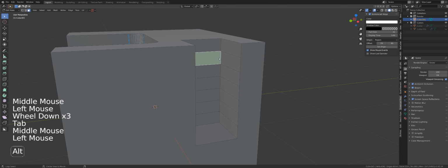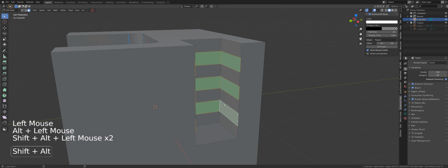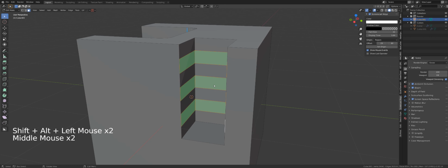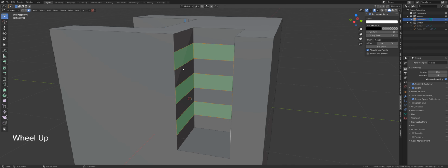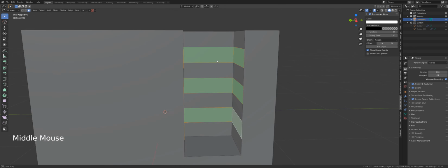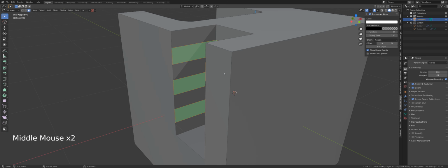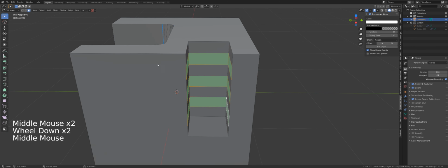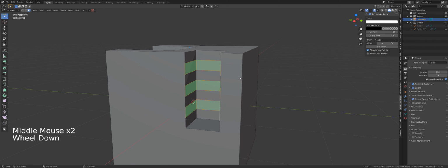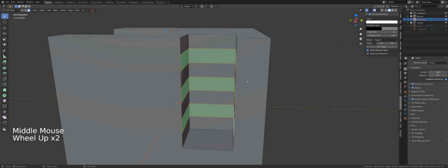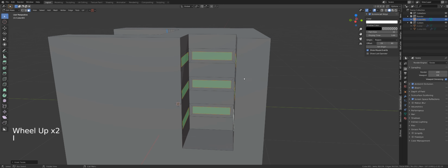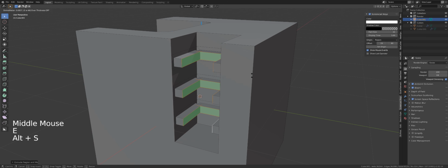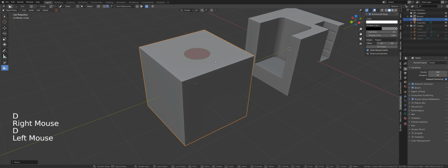So I could control either mesh geometry or add, let's say, loop cuts in a place where it would be rather difficult to do that because it's not a quad, right? It's an n-gon. So if I try to add loop cuts in here, it wouldn't work. So you could do it this way, and then I can manipulate this mesh, right? All those operations are going to work with any cutter.